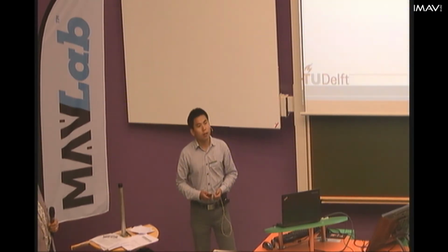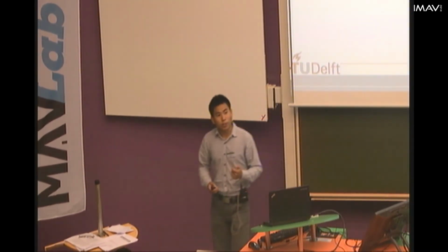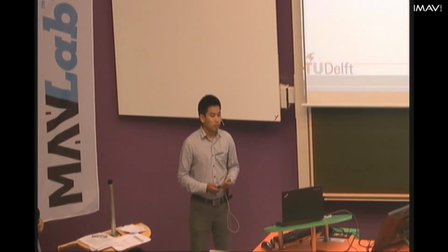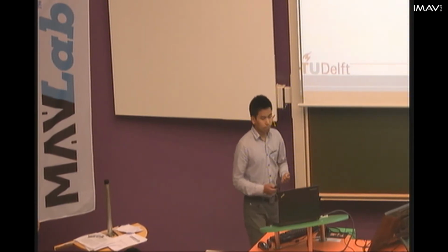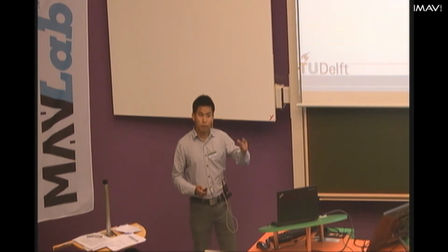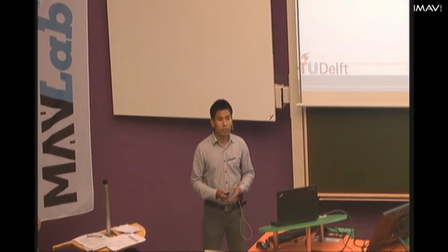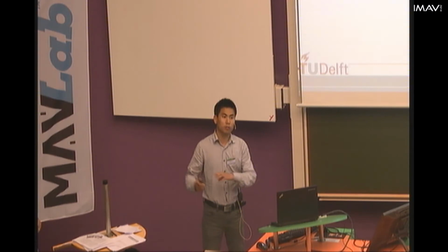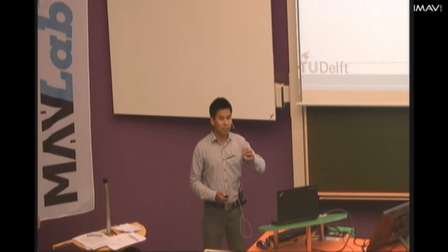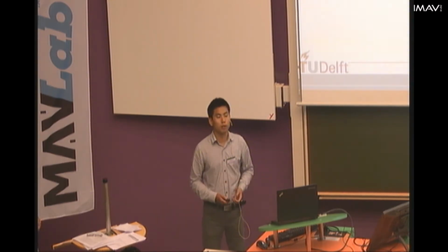As to the first question, I would say the flexibility of the insect wing can be modeled, but the energy efficiency will change a little bit, not so high. So here we represent the wing flexibility with a rigid plate with a torsional spring. This can give us at least a trend about the effect of these parameters on the lift and power.